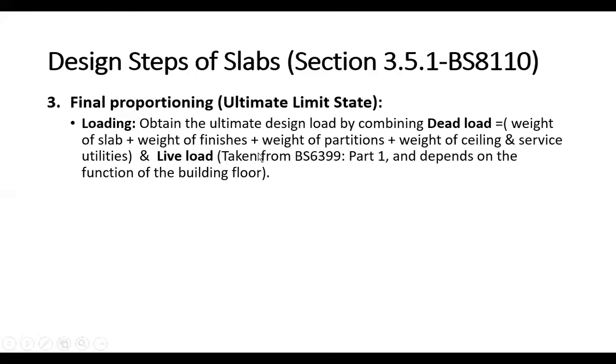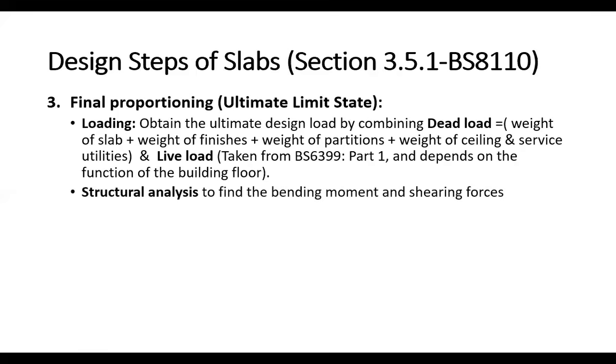If you have finishes, weight of partitions, weight of ceiling and services, all of this also will be considered as dead load. In addition to the dead load, we have also live load, or sometimes we call it imposed loads. We take it from the code, and it depends on the function of your building. Okay. Once you have the loads, you have to go to the structural analysis step to find the bending moment and shear forces on the slabs.